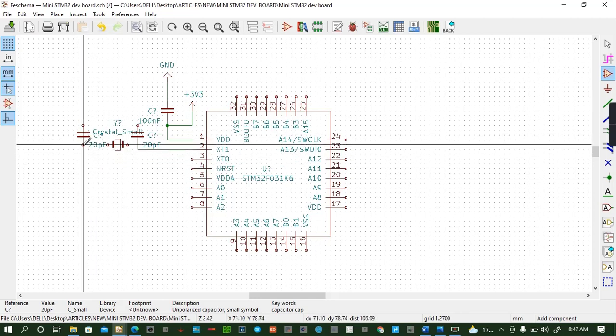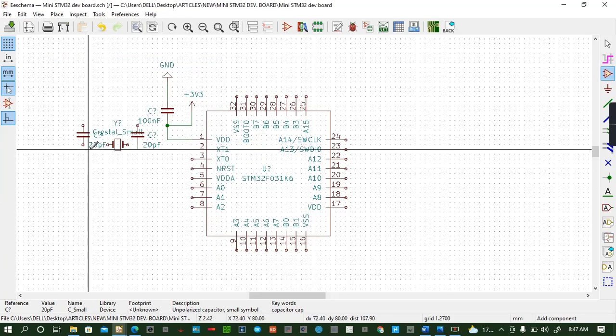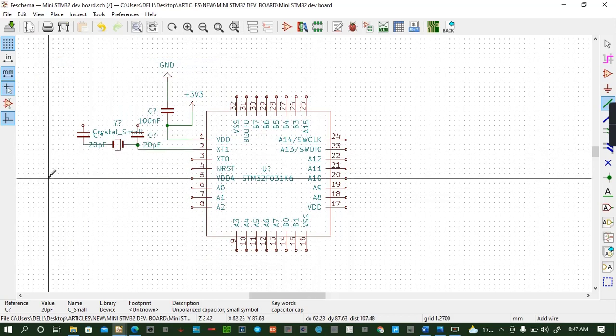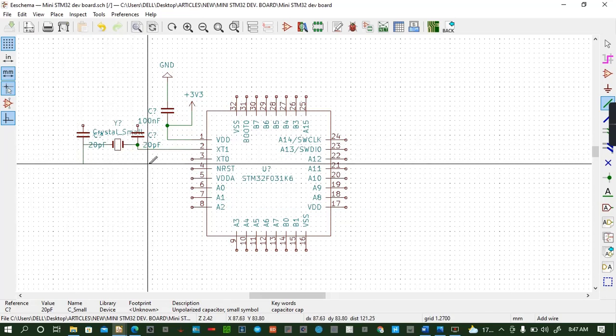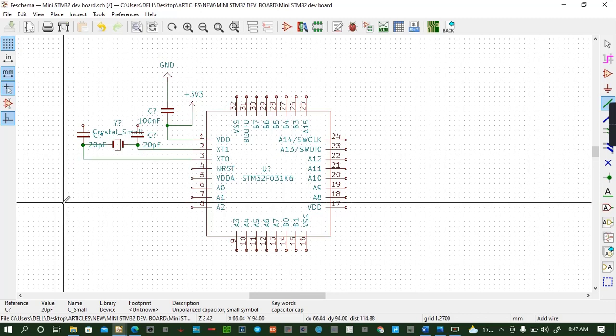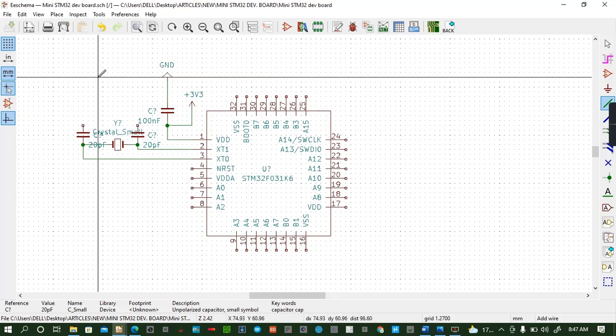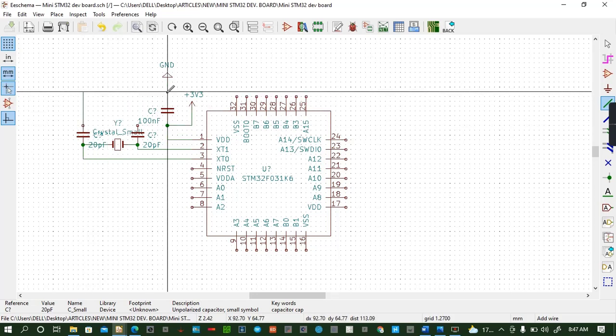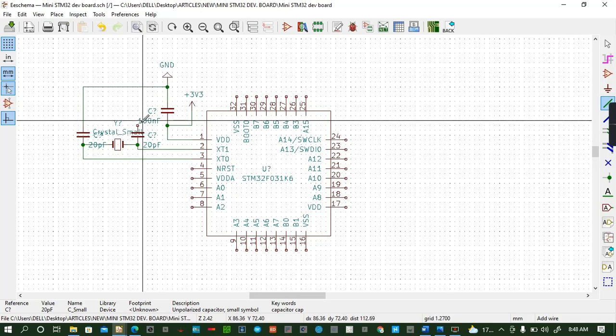And then now add the connection of the quartz. So I need to import wire W for one. You connect this one from here to that point, Control save, and then we move our crystal from there to pin number 3 exterior. From here we go to pin number 3 like that, Control save. We are still doing our circuit. So you are moving in slowly but surely. So we have this capacitor connected to ground. So from here we go to this ground there, the same way as this one we'll do. Control save.